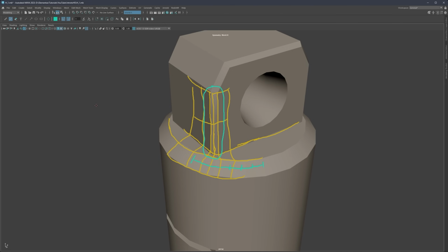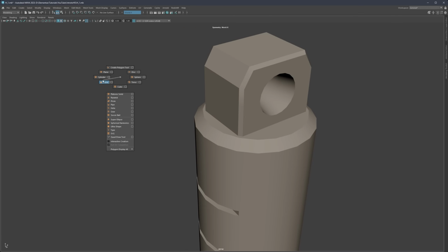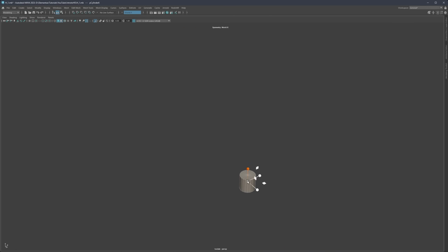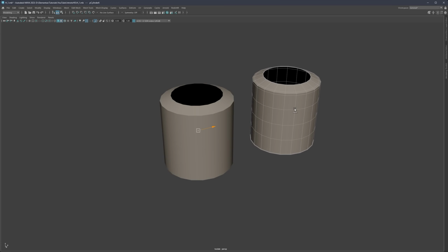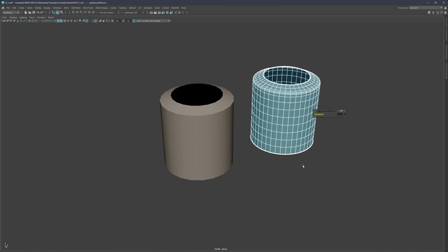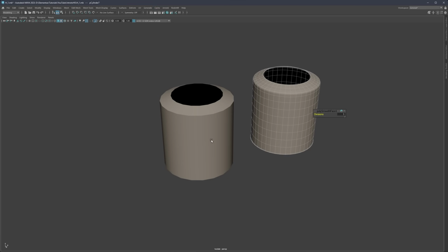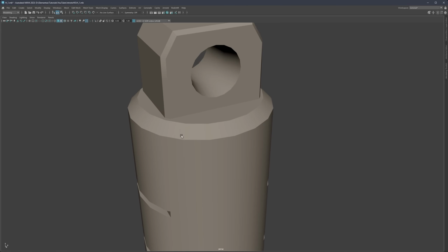And what I mean by start there, let me just also clear this all, it means that if I have a cylinder, just a quick example to demonstrate, we can start with a low level cylinder, and then later we can smooth the cylinder and get more subdivision from there. So we can establish all the general shapes that we need here, and when we think that we need more topology, more shapes, then we're going to continue to more topology, and that will give us enough room to create all the forms that we want to.